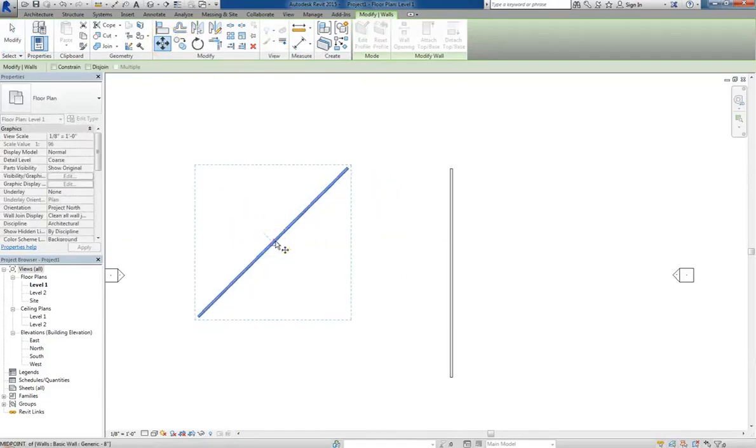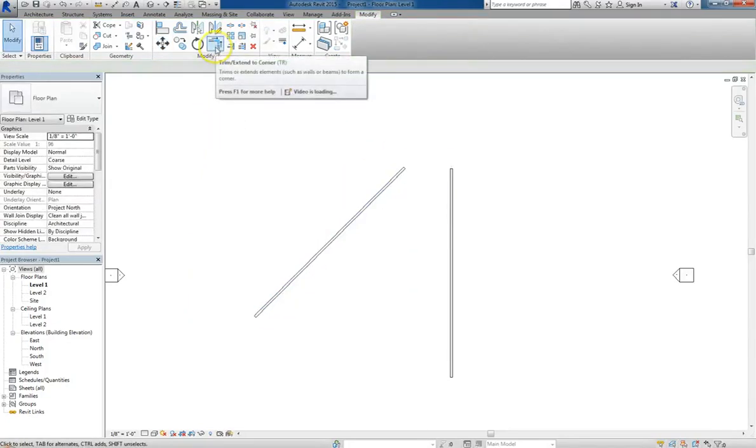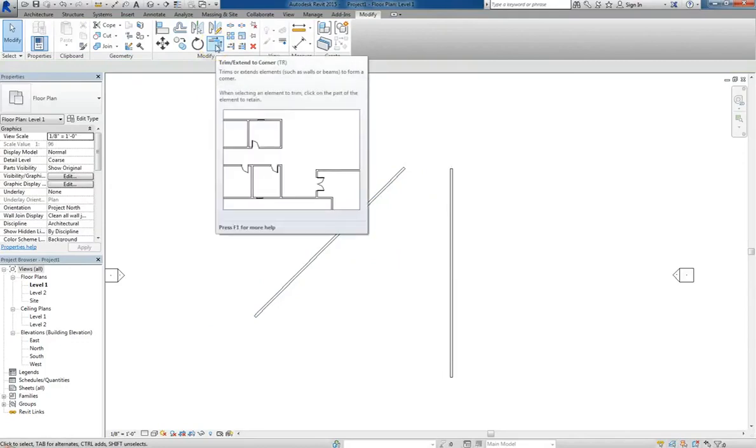We'll just click on the object, click Move, and then we're selecting from where we want to move it to, where we want to move it. We can also add trim or extensions. So still under the Modify tab, we'll highlight that, and a good rule of thumb is that whenever you see